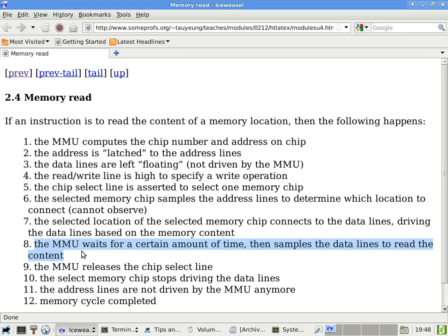So how would DDR2 and DDR3 affect this process? They would affect it, because when you specify which location to read, on top of saying that, you're also specifying burst mode. I'm not sure whether you can specify the number of following locations to read, but there is a way to do it. Either it is an understanding between the processor and the memory chip that it is always 8 or always 16, or it can be part of the bus structure. There may be a few more lines that specify how many locations to read after that.